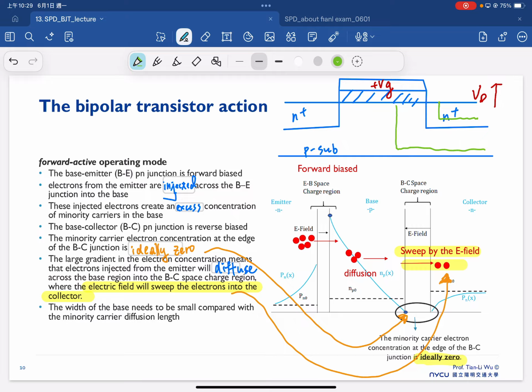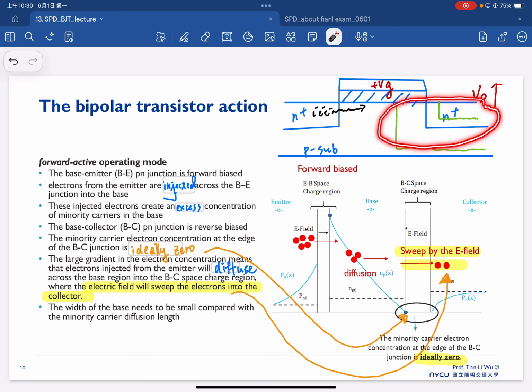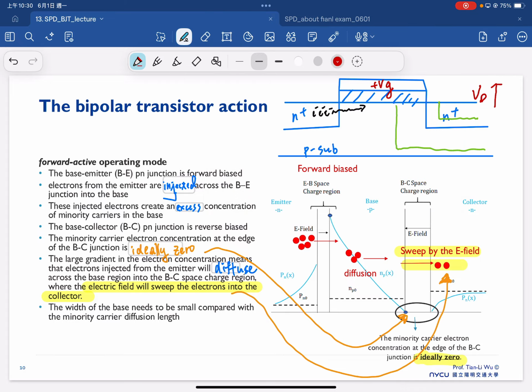And what we knew from the MOSFET is that first of all, electrons, why we call it the source, because that's a source for the electron. So electrons will always start moving from the source region and gradually move into the channel region, where as long as we have this higher drain bias, the inversion charge in the channel will become triangular here.